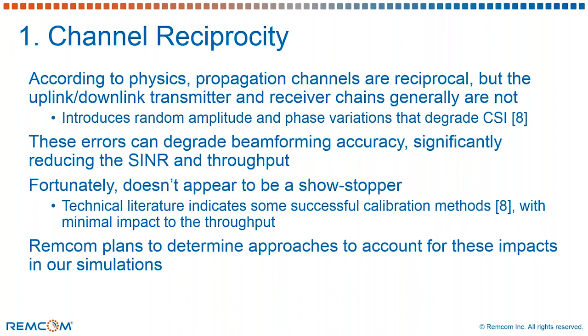Next, we have pilot contamination. MIMO systems use pilot sequences from each UE to estimate the channel. There's a maximum number of unique pilots that's limited by the coherence interval and the RMS delay spread within any cell. When there are many UEs in close proximity in small cells, it's possible to exceed the possible number of pilots.